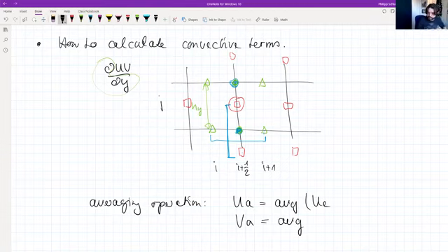And now I'm taking the extended one to also include the boundary conditions, and I also include here the extended mesh. Now, the second index in this averaging operation is the direction in which I would like to average. And it takes two parameters, 1 or 2. 1 means that I average in the x direction, and 2 means that I average in the vertical direction. Now, in this case, I want to get u averaged in the vertical direction to get this point. So I will have the value 2 here. And for v, I want to average in the x direction. So I'll put index 1.